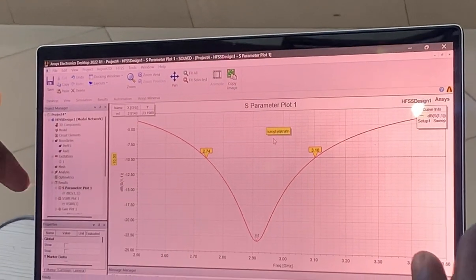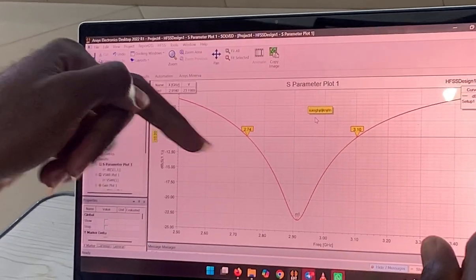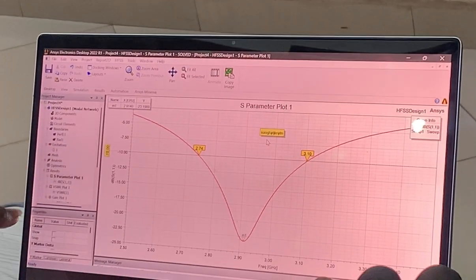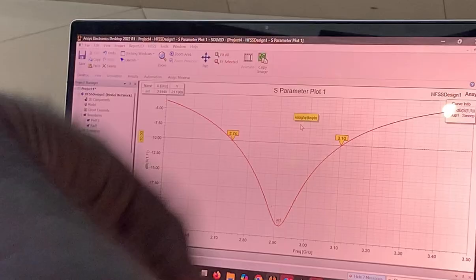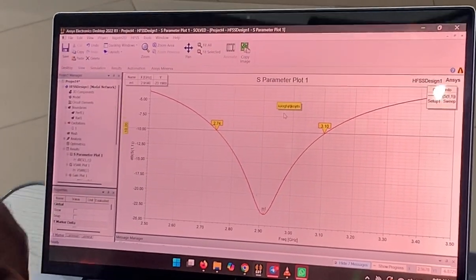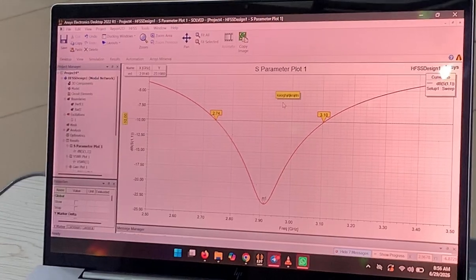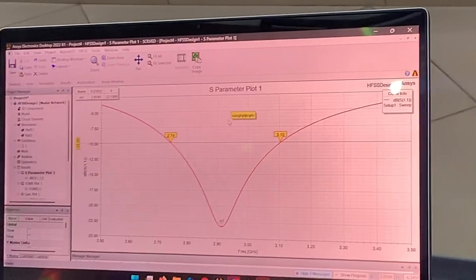And then you do the same for your VSWR. So you add the markers and then calculate the bandwidth and the fractional bandwidth for that as well. The gain, the one that looks like donuts, I don't know what I'm doing wrong, but when you watch the video, you see exactly what you're supposed to do to be able to plot the gain. So that's just it. Thank you.